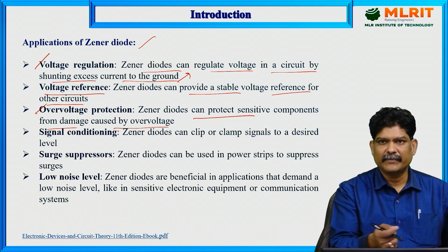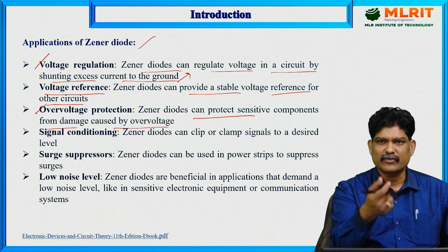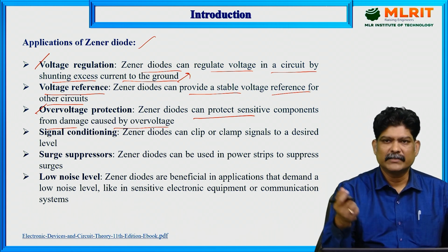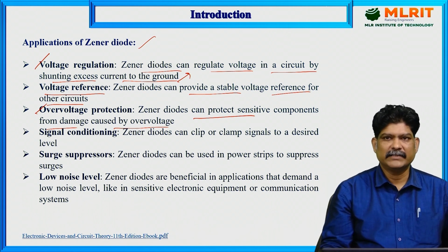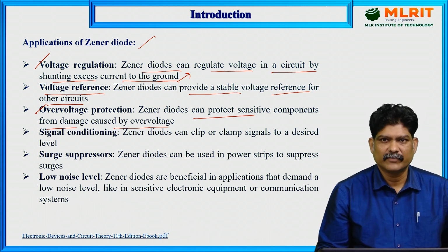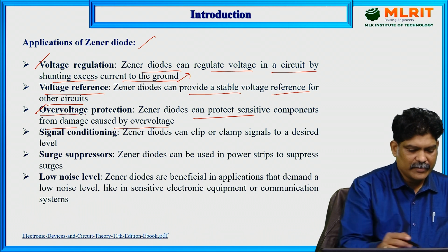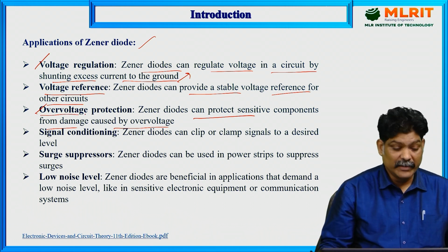If the voltage is greater than the reference or threshold voltage, your gadget may get damaged. To avoid such situations, we require Zener diodes for overvoltage protection.